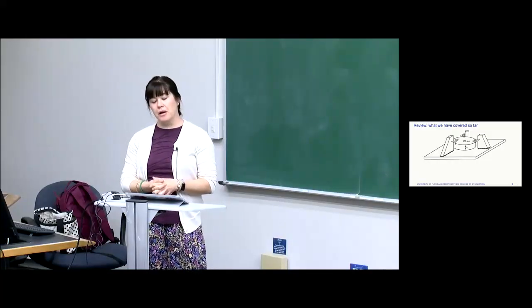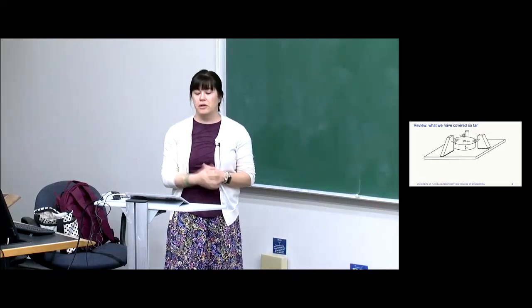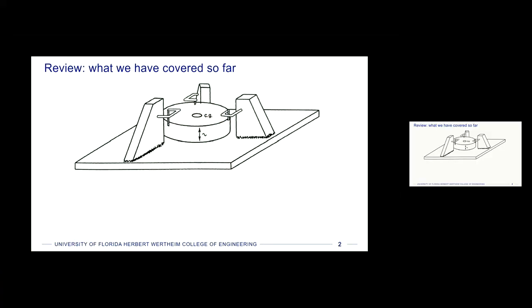And then the problem told us that this component was made to be flexible, right, as it's bouncing around in the back of a truck. And so the amplitude of the oscillations, up and down, so that would be 2 times the amplitude, was approximately equal to the magnitude of the deflection or the stress as it was sitting stationary, right?